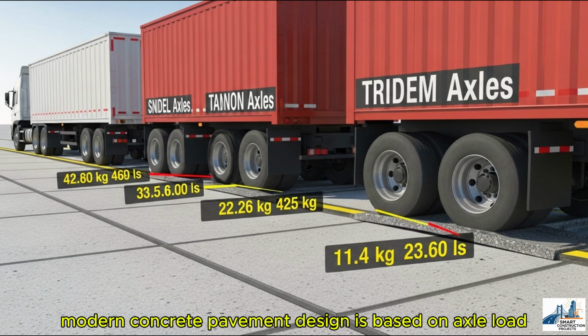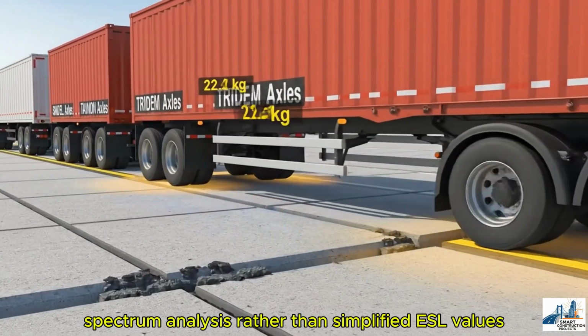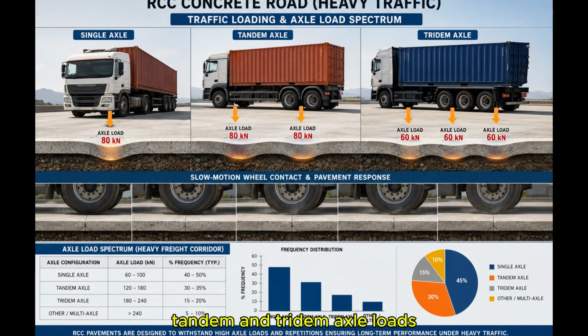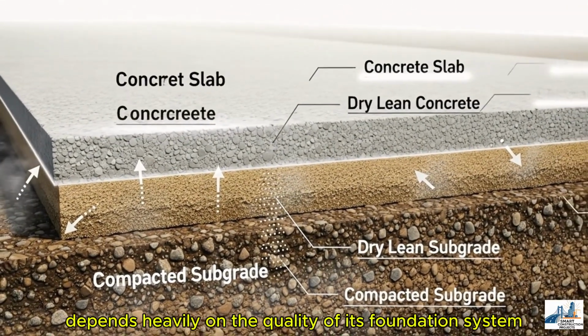Modern concrete pavement design is based on axle load spectrum analysis rather than simplified ESAL values. Heavy highways experience single, tandem, and tridem axle loads, often exceeding legal limits, making accurate traffic modeling essential for long-term durability. Yet even the most advanced traffic modeling cannot compensate for poor ground support. The performance of a concrete road depends heavily on the quality of its foundation system.